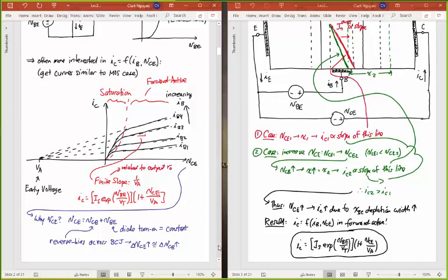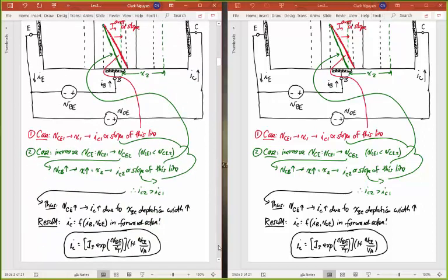And the first thing that we need to worry about if we want to design an MOS or a bipolar transistor circuit, and in this class we'll generally be looking at amplifiers, is we have to bias these devices correctly. And so what is meant by biasing is DC biasing. We want to make sure that we can establish a certain operating point. So I defined last time what an operating point is. That's the voltages at all the nodes. That's the currents running through all the branches.